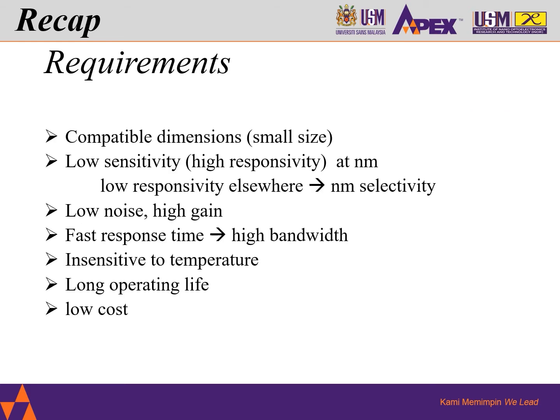What are the requirements for a photodetector? Of course, we want a photodetector with compatible physical dimensions, where small size is more favorable. We also want high sensitivity with high responsivity at the desired wavelength, and low responsivity elsewhere for wavelength selectivity.